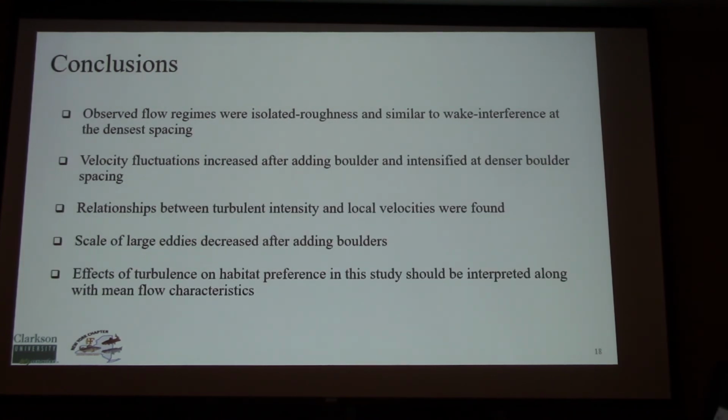So, summary and conclusions. We actually observed just isolated flow regimes, and at the densest boulder spacing, we had some signs of wake interference flow regime. Velocity fluctuations increase after adding boulders, and it intensified at denser boulder spacing. Also, we found a relationship between turbulence intensity and local average velocity, and